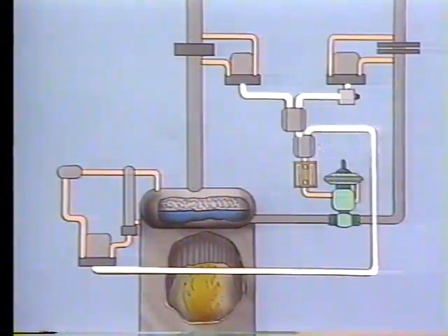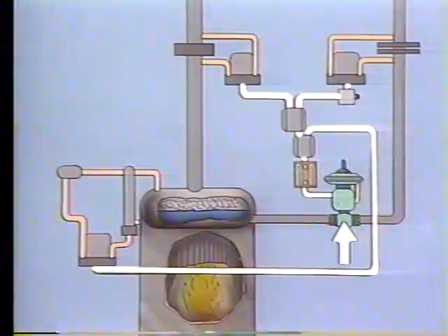The feedwater flow controller compares the signal from the ratio controller to the signal from the drum level transmitter. It computes any difference between these two signals and compares that difference to set point. The feedwater flow controller sends a corrective signal through the hand auto transfer station to the final control element. The final control element repositions the valve to change the flow of feedwater into the drum. At this point, the feedwater flow transmitter measures the change in the feedwater. It produces an output signal that represents the new flow rate.